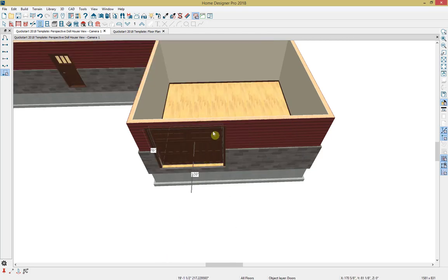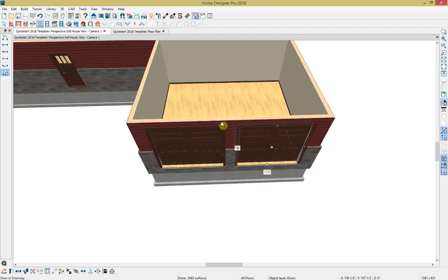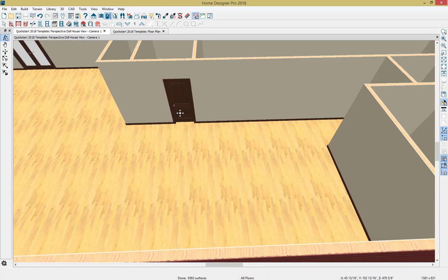So I've selected our garage door, and I've selected Reflect About, and then I can marquee about other objects, and you'll notice that I get that black dashed line indicating which object will reflect this copy of the door about. So once I'm happy with the object that I've got marqueed, I can just click once, and a copy of that door will be reflected about that object. If we use our mouse orbit tool and go back to where we dropped in that interior door, we can select that interior door, select copy, and then just paste a copy of it wherever we want.